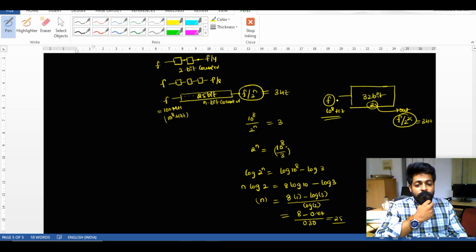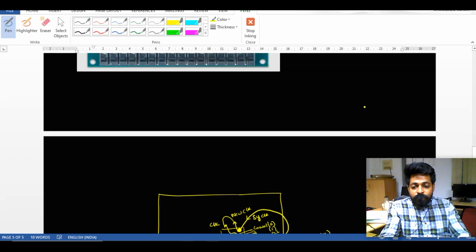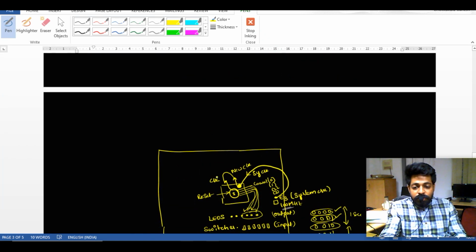So now what I do is, whatever the system clock that I have at a very high frequency, which is generated across the crystal oscillator, now using my system, using this kind of a digital circuit which I'm trying to implement over here, that circuit will take a system clock and will be generating a new clock with the frequency of 3 Hz.